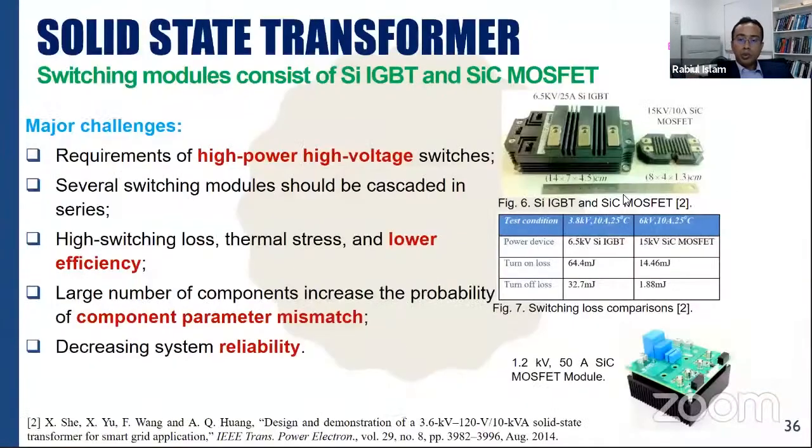Great. So if we look at the ongoing industrial development in this sector, industries are actually helping by introducing the latest power electronic devices. For example, silicon carbide. Silicon carbide can handle 15 kilovolts, and its switching on-off loss is much lower than the traditional silicon-based devices. Its size is very compact. So therefore, it is not really difficult to develop that type of system in the future, right?